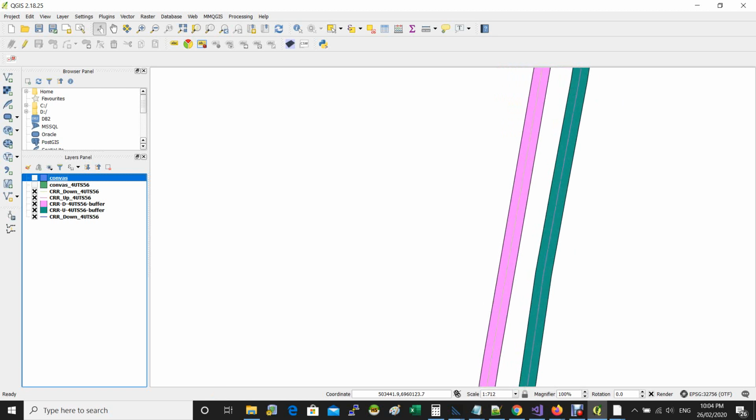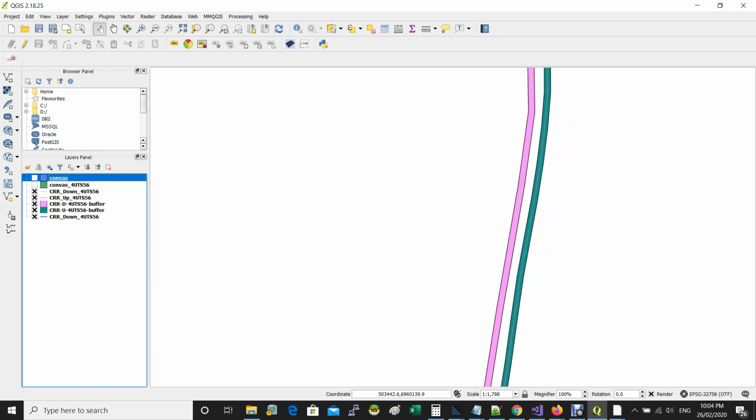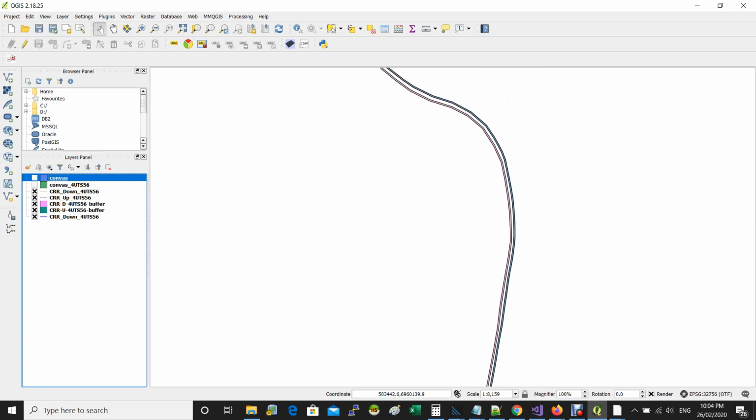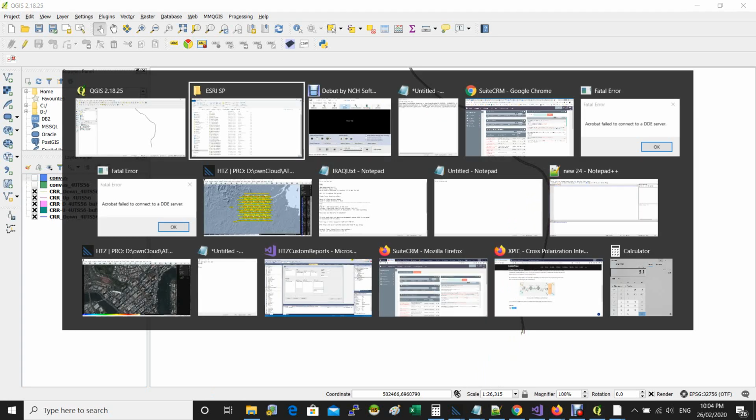In fact, I received only the center line, and I had to convert it into a polygon. There's a function in this tool to buffer the line to the left and to the right, and to build a polygon. So these polygons are the minimum data you need to have available before you go ahead and build the tunnel model in the software. Okay, so this is what you have, and you want to do RF predictions like leaky feeder in a tunnel environment.